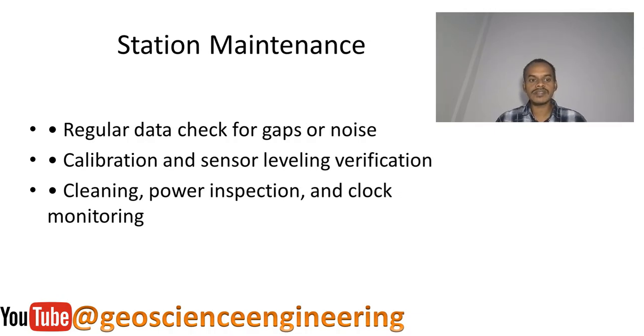And the station maintenance, how the calibration is done, how the leveling is done, how the cleaning should be done, how the power inspection will be done, how the clock monitoring should be done, and regular checkups, so that we never get any gap in the noise or any gap in the data.